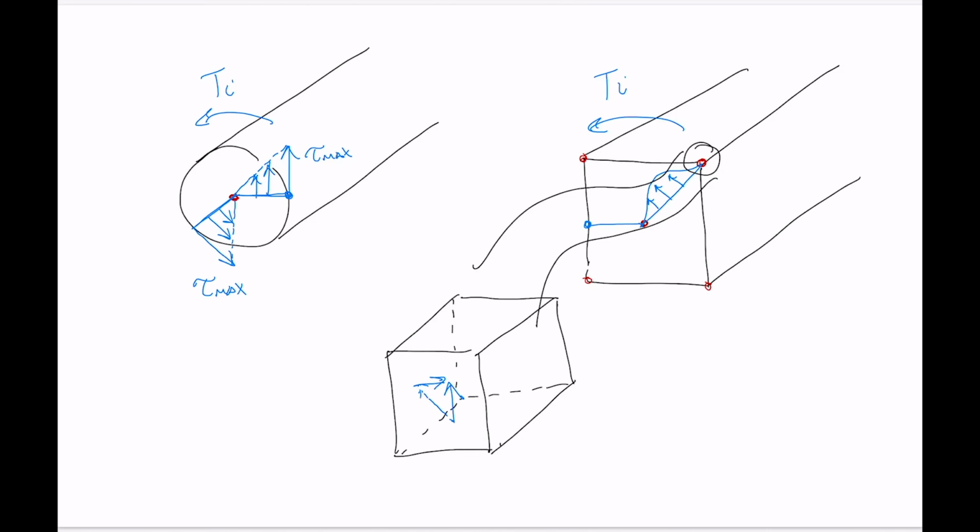So if we look at the consequences of those shear stresses, let's just deal with one of them, and for the other one the situation's exactly the same. So let's just look at that vertical shear stress here. So I'm going to erase the other ones. So this is shear stress tau, and it's acting on area dA. And this is a cube of material, so all of the sides have the same area. And we know that the product of tau dA gives us a force.